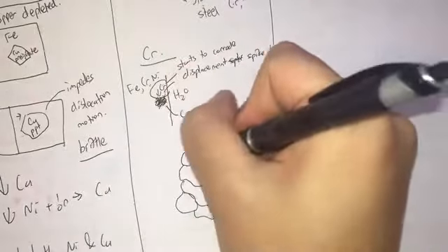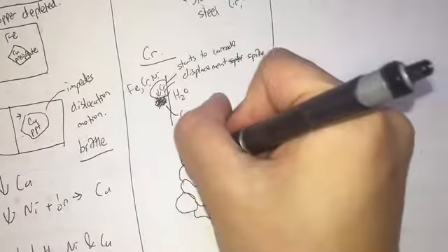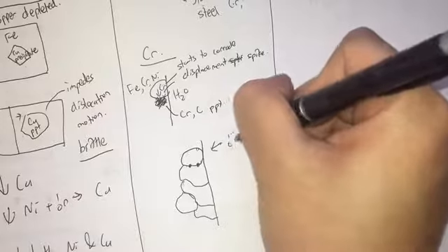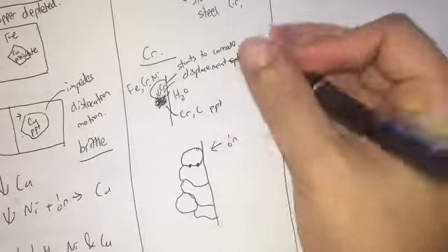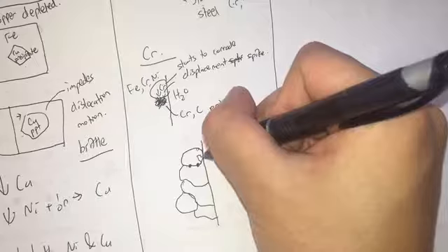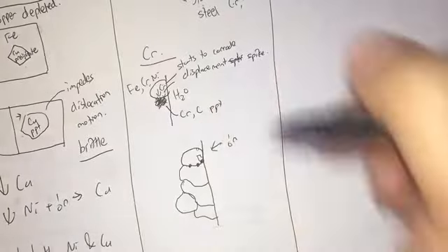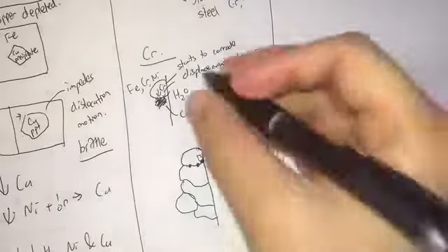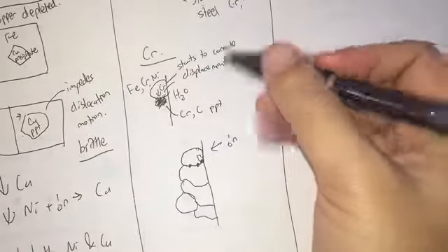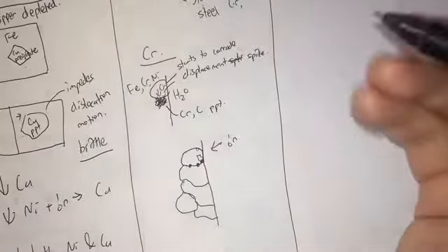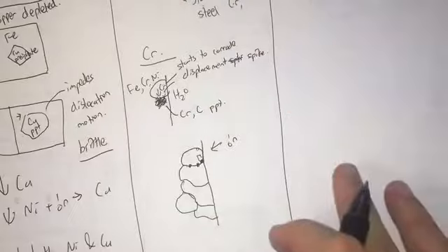And what we will find is that all these precipitates tend to cluster around the grain boundaries when radiation hits. When fast neutrons hit this, they'll cause a displacement spike somewhere here, so that the chromium will tend to cluster at the grain boundaries. Why do they cluster at the grain boundaries? It's because diffusion happens faster at the grain boundaries, because the atoms are less attached to the lattice. So let's say you have this surface, okay?